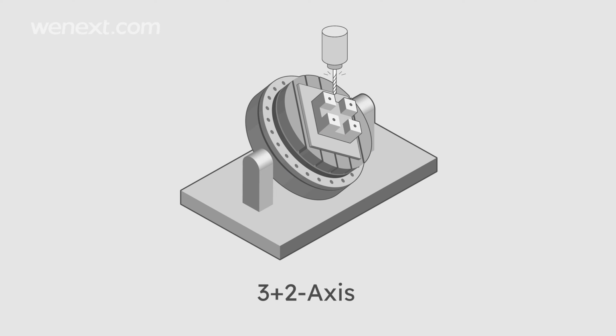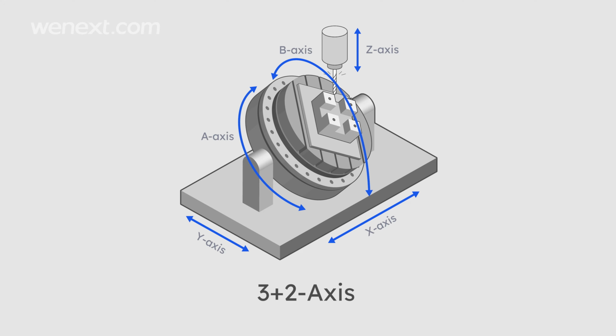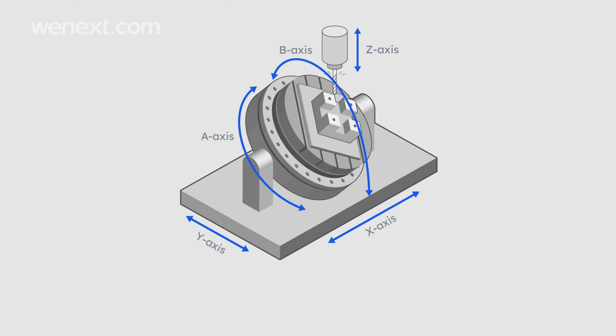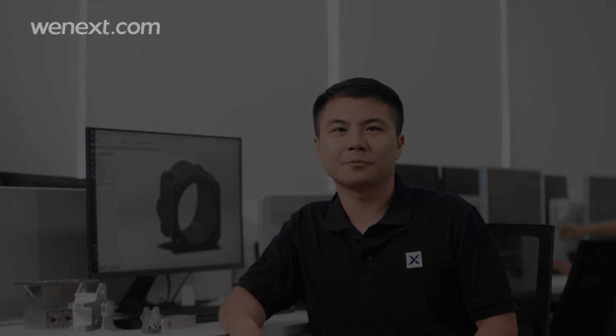By adding the C-axis that rotates with the Z-axis and working with X, Y, Z, and A, 3+2 starts producing parts with tight tolerance. In 3+2, the X, Y, Z, and AC rotation axes are working independently, which means the workpiece can be rotated relative to the cutting bit to any compound angle. If you need to produce parts with deep cavities and complex structures, 3+2 can produce a part from any direction without manual rotation, making it a suitable option for you.